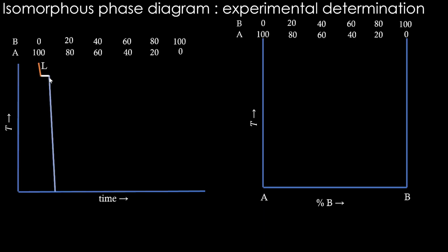When the material cools, what we have to keep in mind is that the heat extraction is happening at a constant rate. The amount of heat taken out per unit time is kind of constant. If that is the case, then the temperature should be falling gradually, right? But that is not going to happen. You will be seeing regions like this where the temperature is not at all falling, but the time is increasing. But remember that heat is extracted out. So this is what happens when things are exothermic in nature. When the transformations are exothermic, the heat is coming out of the reaction or the transformation, and that holds the temperature. This kind of thing happens. Right. So this is how the liquid cools to solid state.